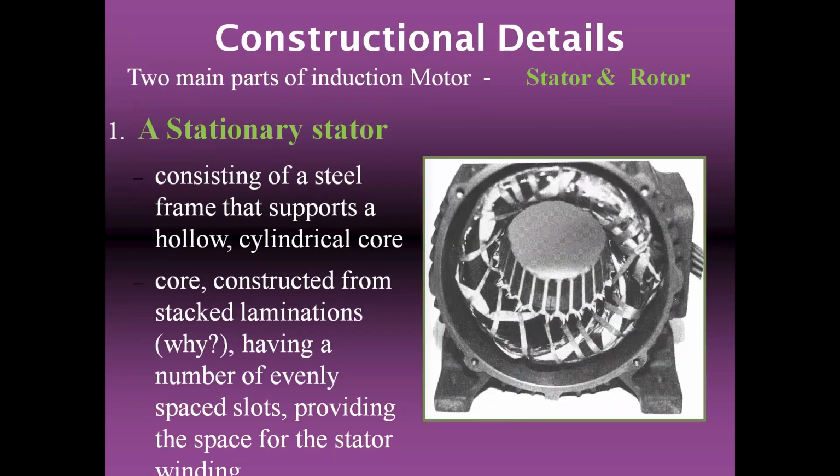There are two main parts, stator and rotor. If we talk about the stator, this outer frame is casted, but inside it has a laminated core. It is a laminated silicon steel core, which has slots on the inner periphery. In those slots, we do the winding, a distributed three-phase winding.